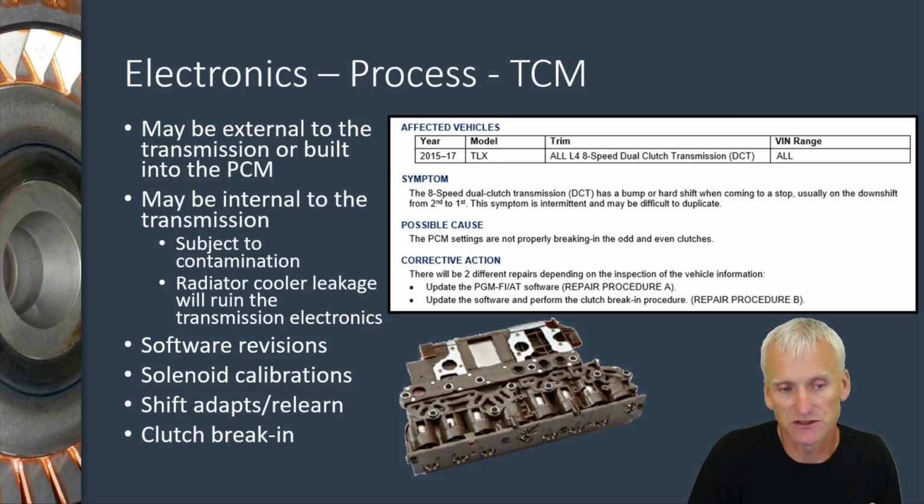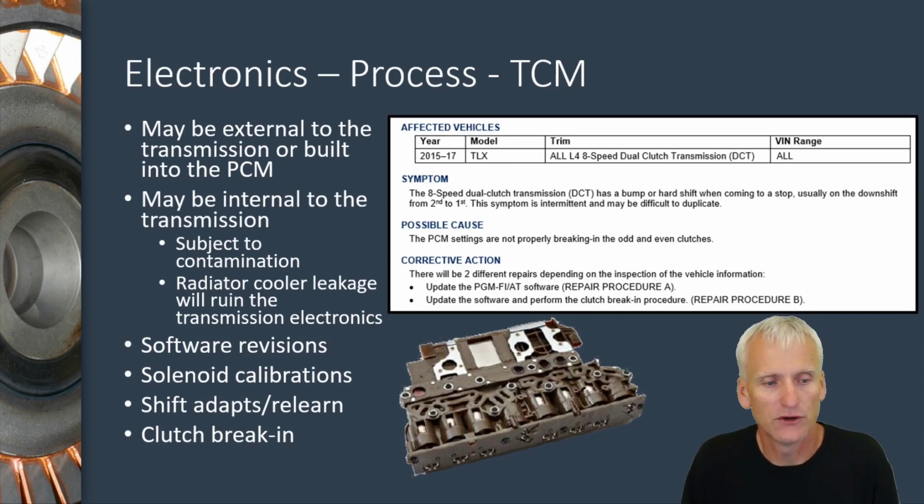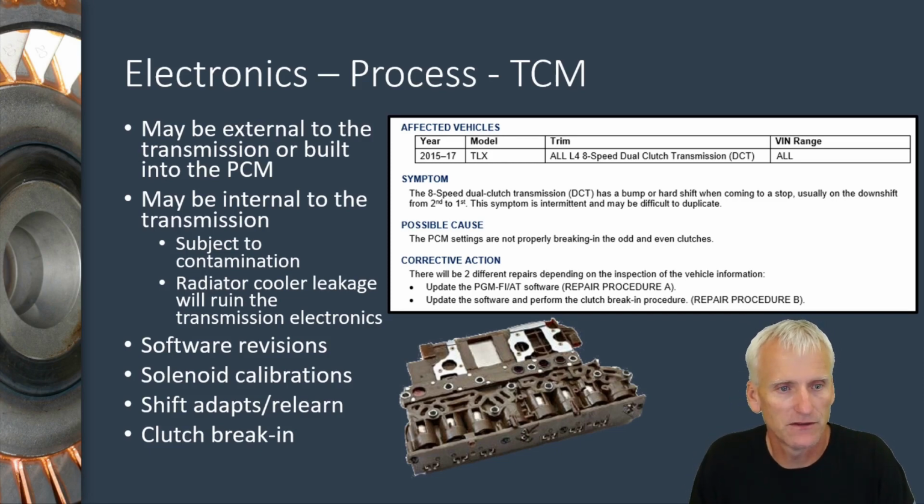So either the transmission shifts smoothly at cruising, kind of light foot throttle accelerations, or the transmission shifts firmly under wide open throttle, so we can keep this thing durable and lasting. But there's other things that we need to think about when we think about the TCM. So we want to make sure we have the proper software versions and updates.